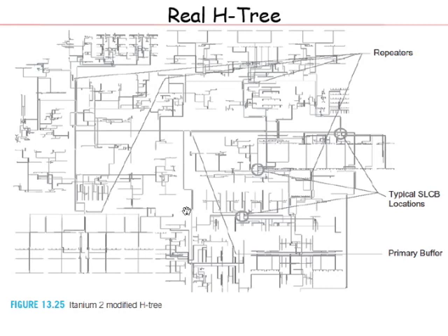Okay, so this kind of modification happens, as I said, in an automated way by the tools. It's very difficult to do it manually. What happens is just delay calculation. You have to keep calculating the delay and keep adjusting the delays and make sure the delay from the source of the clock to the clock input of the flop is the same for all the flops. That is basically the requirement to ensure you have no skew.